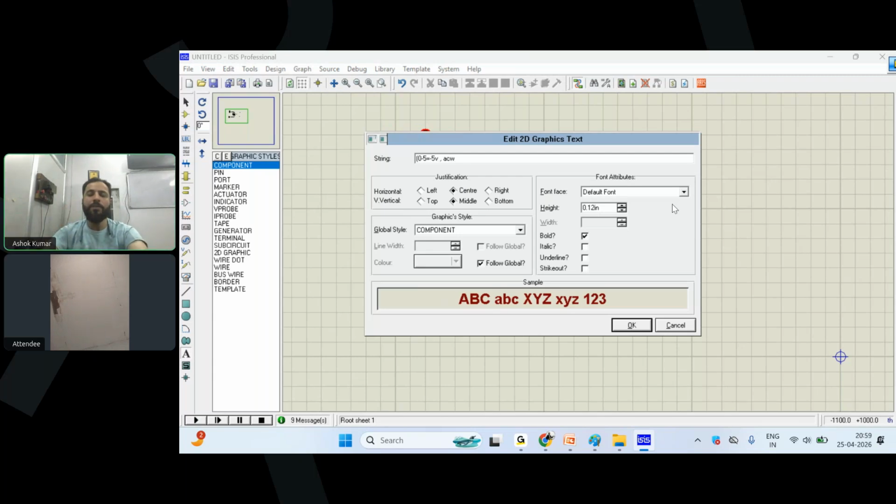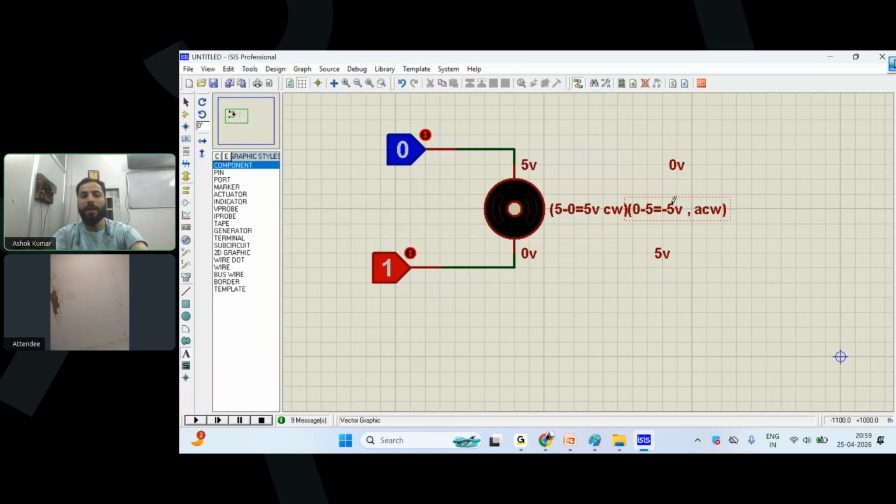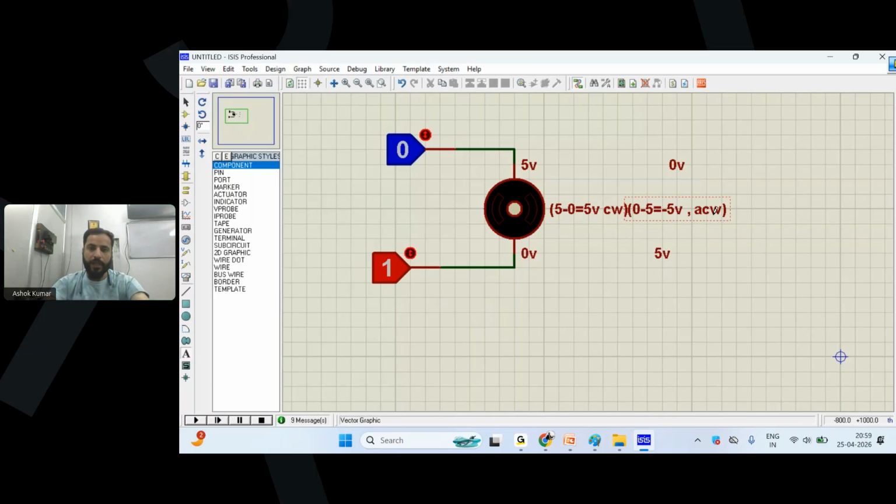This is the concept we have used to move your motor forward and backward. If you have to go forward, it should be clockwise, and for backward, it should be anti-clockwise. Now, what was the operation of left and right? Left and right is also very simple. Whichever side you have to go, stop that side. If you go left, move the right motors and stop the left motors. If you go right, stop the right motors and move the left motors. Correct? This is a very simple concept.